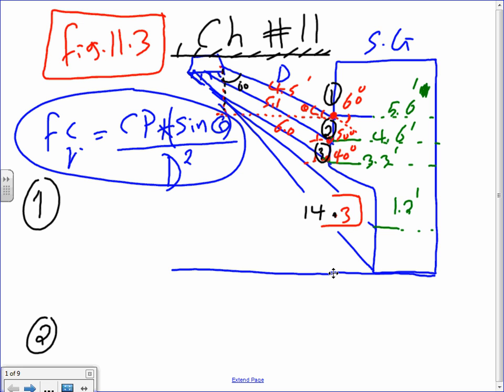Very simple. You take the foot candle vertical calculation, multiply it by the candela power, the lumens, times the sine of the angle. You see the angles are right here. The sine of these angles. The sine of the angle, that's 60 here. The sine of the angle, and then you divide it by the square of the distance. Any comments, guys, about what this example is all about?